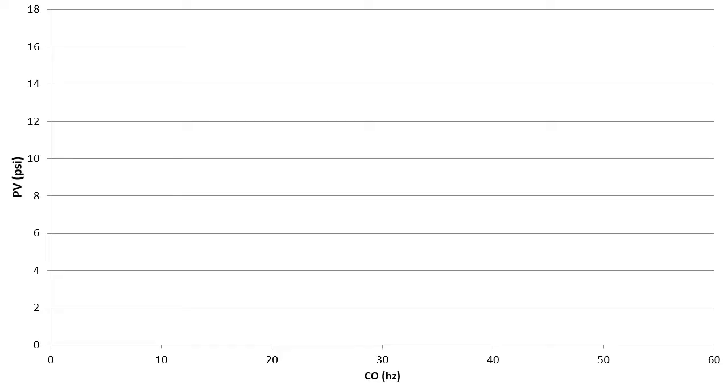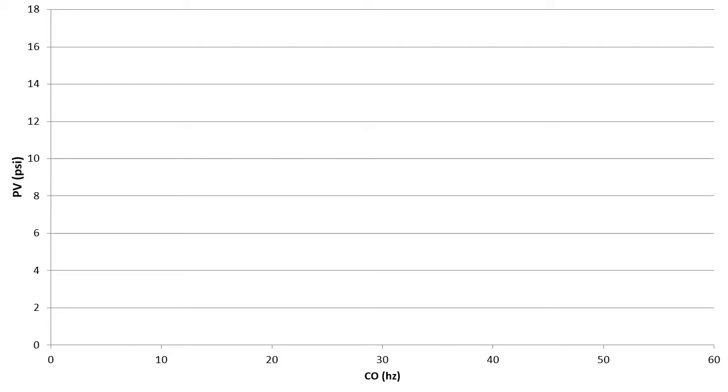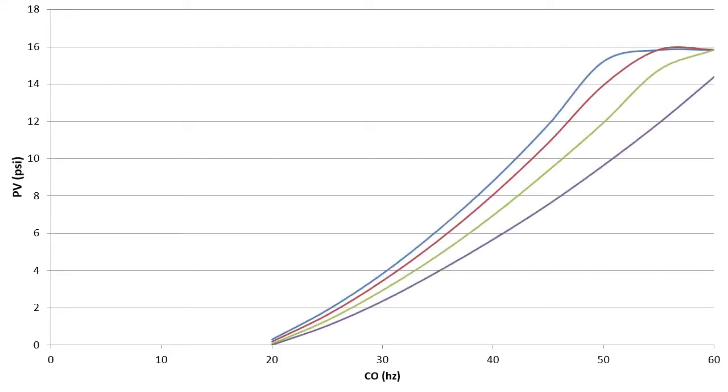In the quick start videos, we ran our system across all possible drive speeds and all possible loads to produce these curves. We saw that as the drive speed increased, the pressure increased, which told us we had a forward-acting system. And it did it in a roughly linear fashion between these drive speeds. That's important. The more linear a system is, the better PID will work.